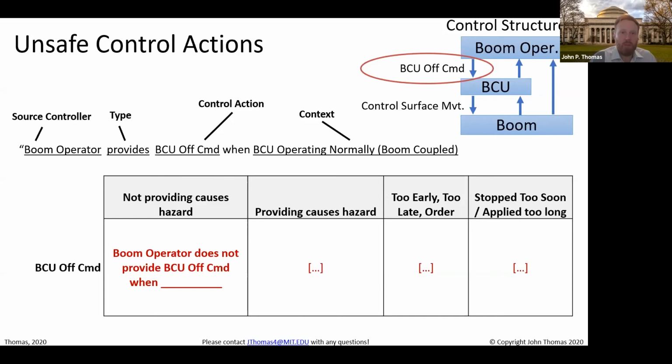Yet the forces on this boom could potentially be very huge. Both the forces that are felt and sensed if we're in the airstream, and the forces that are commanded are very powerful. So it is physically possible that this boom could be damaged by erroneous or unsafe commands from the BCU. So if that thing starts malfunctioning, or if it starts sending unsafe commands, our only chance here is to turn off the BCU.